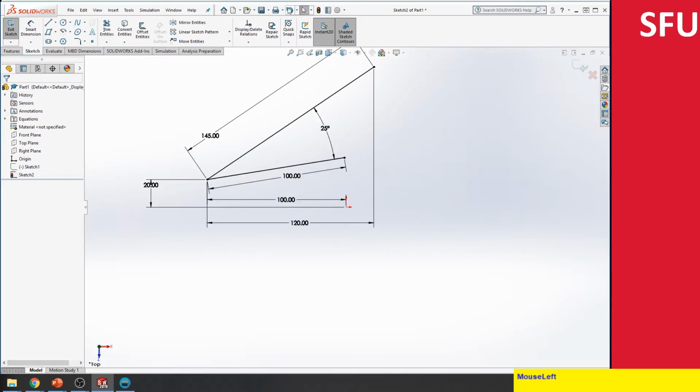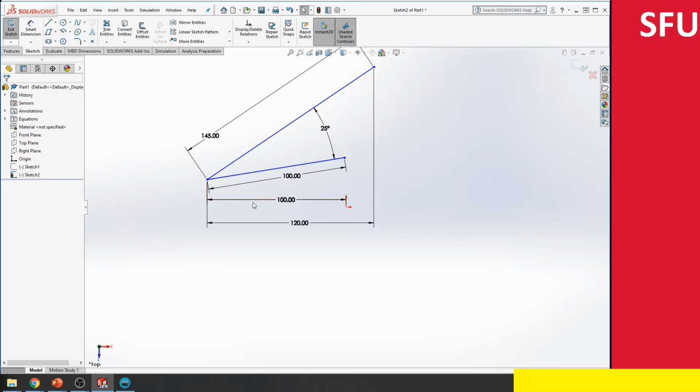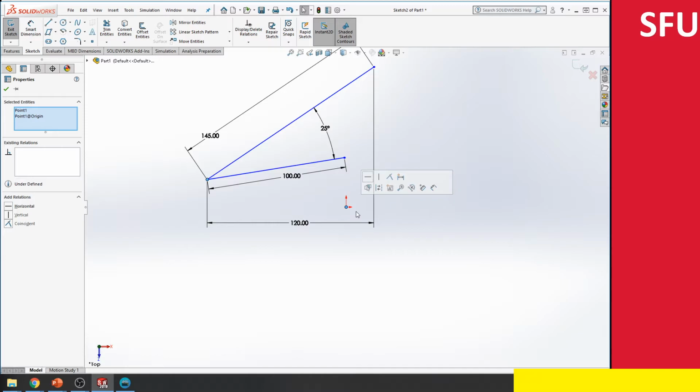So instead what I can do is I can delete this constraint over here, and then rather than specifying the dimension, I can just make this point coincide. The way I would do that is hold Control and select both of the points. So now it gives me the different options. Do you want to make it horizontal, where they're basically both on the horizontal axis?